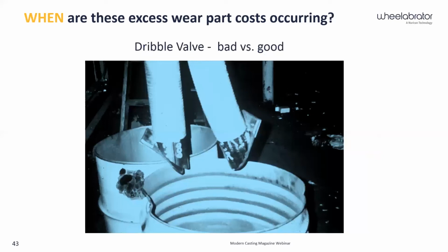Another thing I'll key in on from a safety standpoint: always make sure that that is above the barrel. Never let it protrude down into the barrel, because it will fill up with shot then, could climb all the way up your blast hose and eventually fall off, and there could be 200, 300, 400 pounds there.